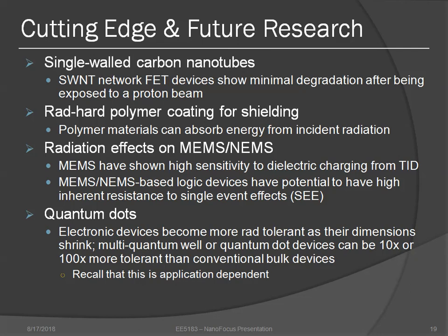They took some control measurements of transfer characteristics before proton irradiation. The devices were then exposed to a proton beam, and the same characteristics were measured after irradiation. They reported that none of their devices, and they had about 26 samples, exhibited any significant altered electrical changes before and after proton irradiation. They claim that because their proton beam conditions are comparable to the aerospace environment, CNT-related devices hold promise for future space applications.